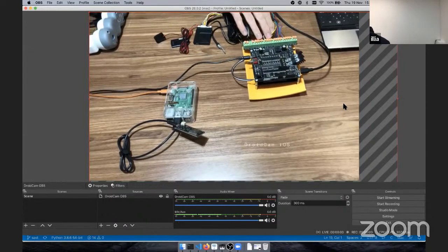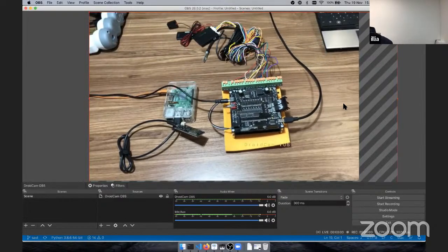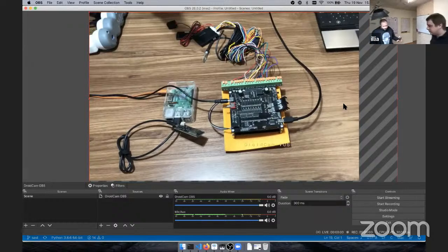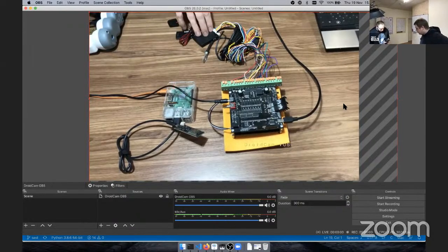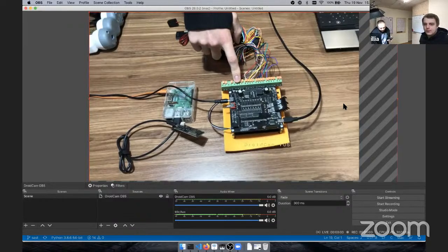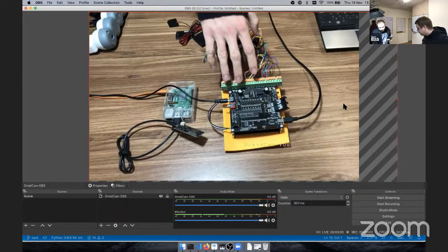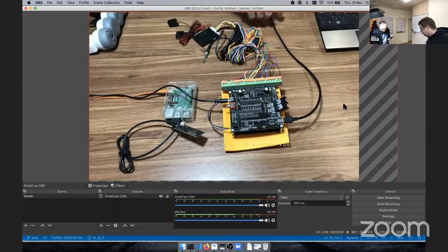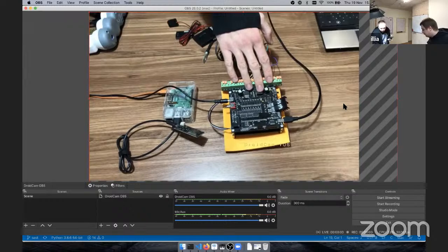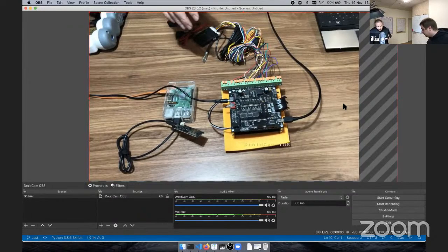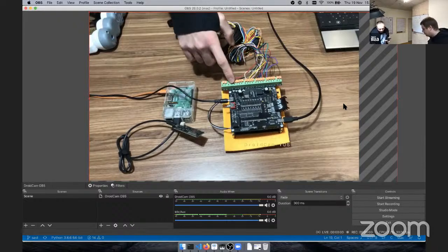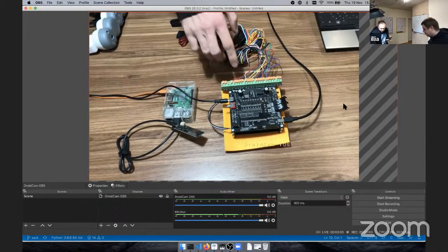So basically what we have done is, this device is actually, I'd say, a middle ground between your laptop and your actual device. Right here you can see a car alarm system that is connected to this car emulator of sorts, because here we can emulate practically any activity present on a vehicle, and through the USB we can push updates to this middleware, and for instance use the CAN frames that we have collected from the real vehicle to emulate it and to see if this device performs well under these conditions.